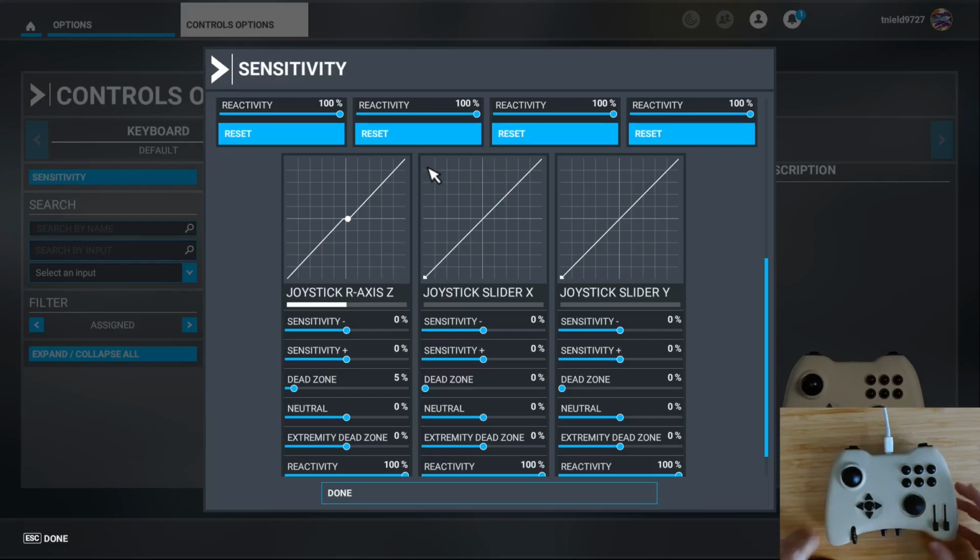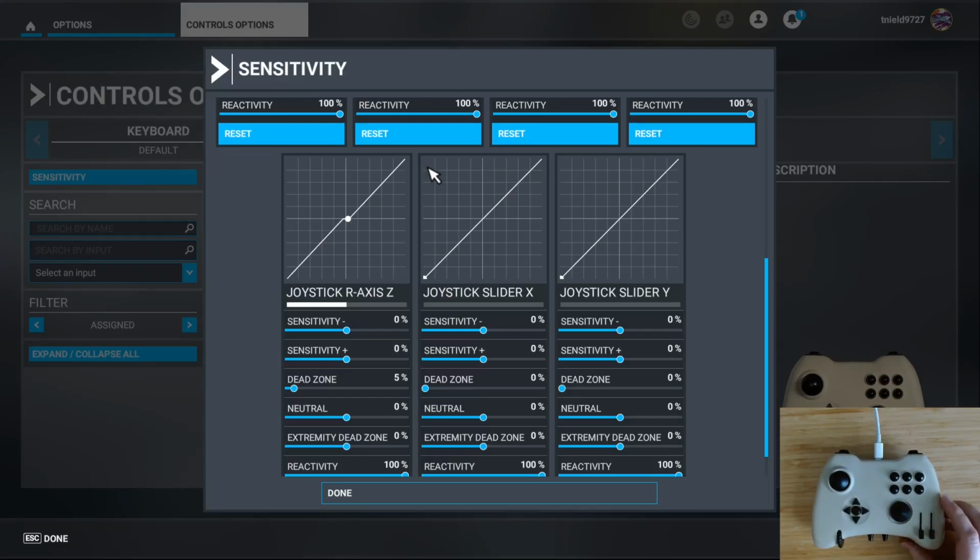Maybe you'll find you need to do more, and if you're finding that your rudder is behaving wildly outside of that center, you probably need to do a firmware level calibration, which is documented, and that'll be a separate video. But you can do the dead zone.